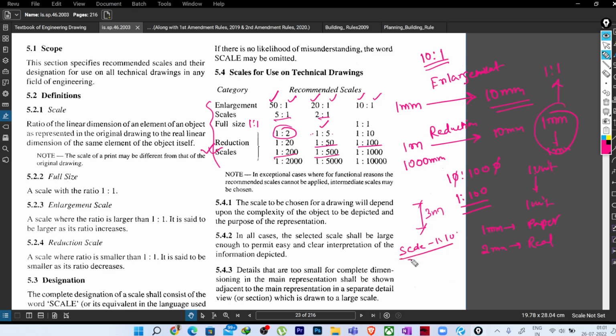And in the area where you write the notes regarding this particular drawing, you have to write that this drawing should not be scaled. That means the scale factor you have provided is just to make one understand how you have reduced, but this scale factor should not be multiplied with the dimensions provided, because these dimensions are the actual dimensions, not the scaled dimensions.